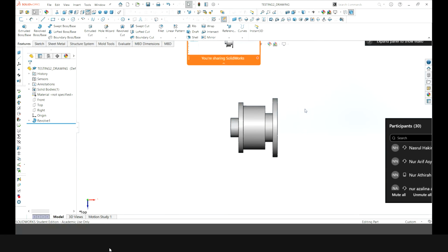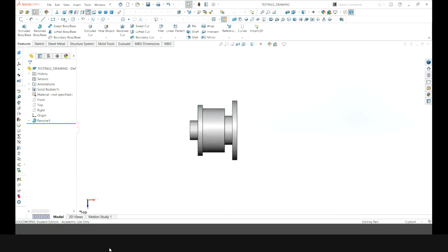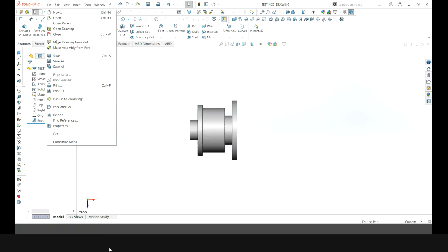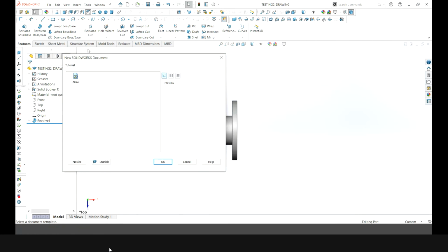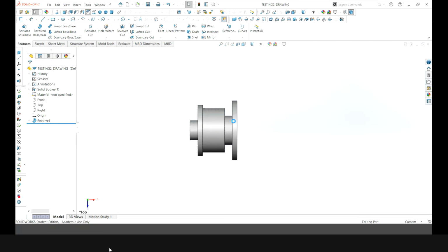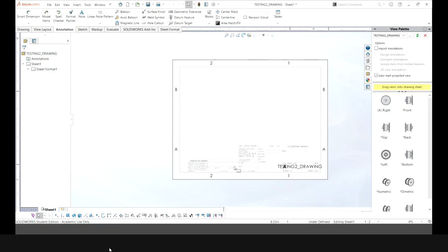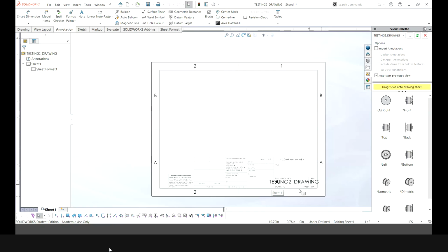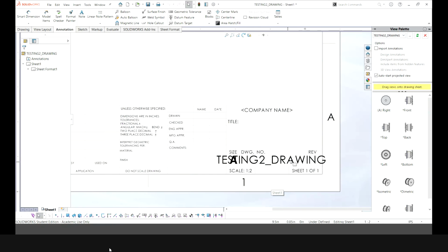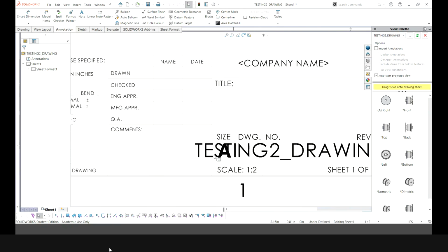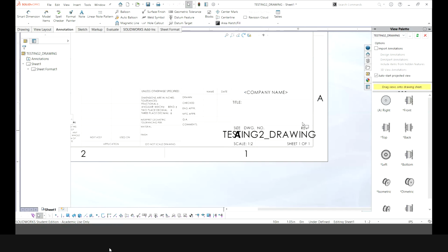And then when you want to make a drawing, produce drawing, go to where? File, and make a drawing. Actually, you have a part, you make drawing for that part. Click part, make drawing, draw, and then OK. Okay, this is a standard template. Just now I mentioned about SolidWorks standard template like this. Sometimes ada setting kat sini size dia besar. This is a link with the name. Dia akan baca testing dua drawing. You can adjust and edit.